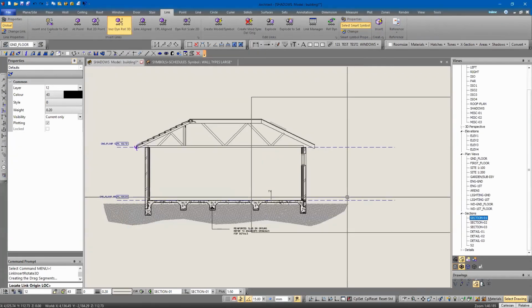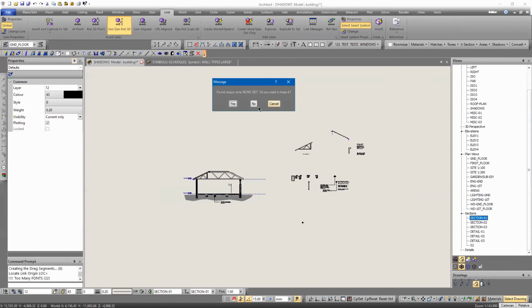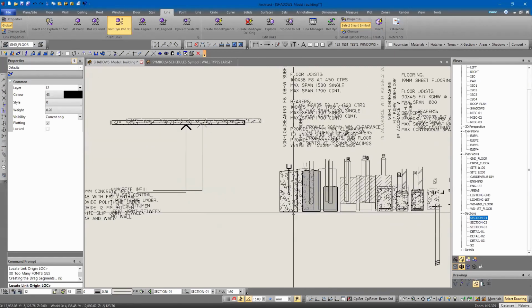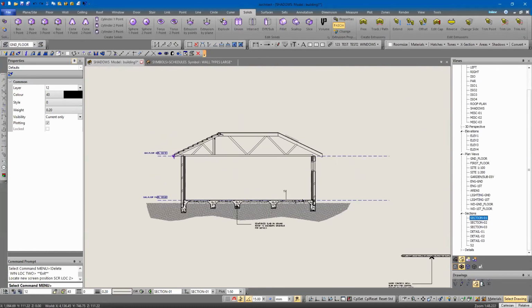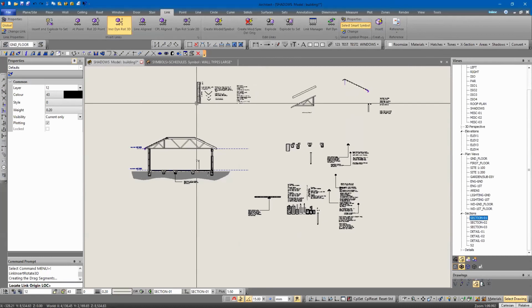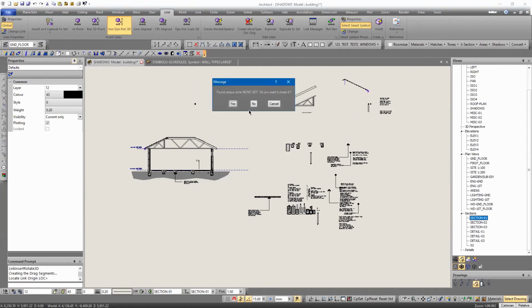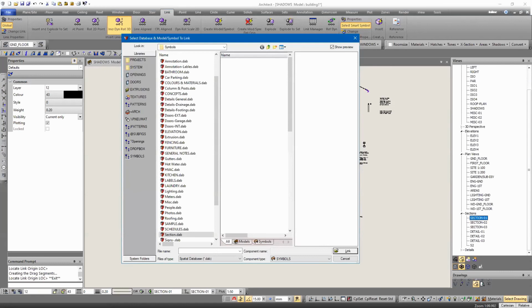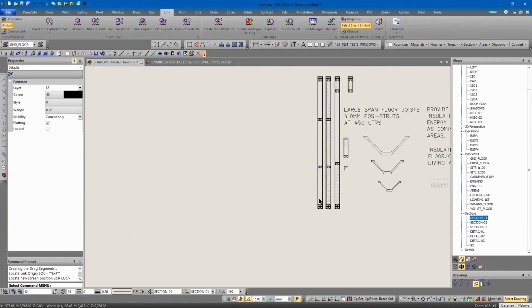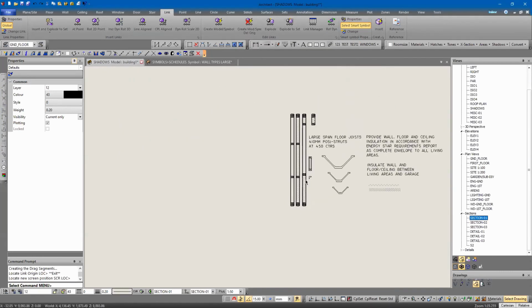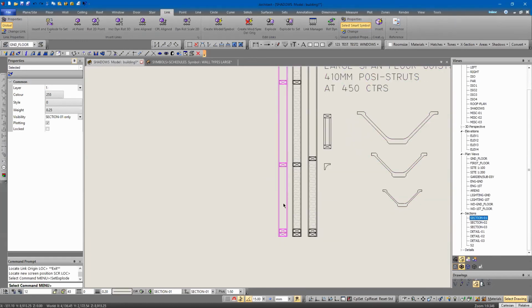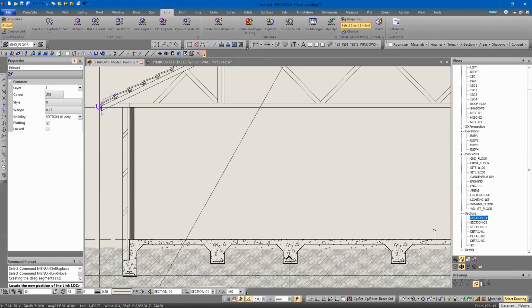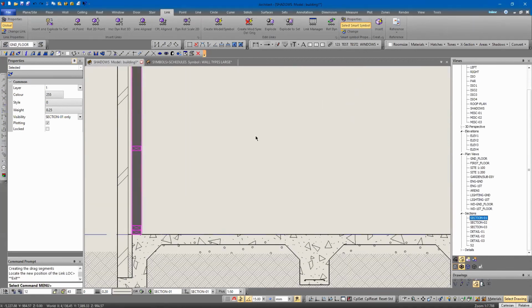We've got a range of things for footings, for stumps. So if we're doing stumps, we just bring those in. So that's sort of the basics of what we do with our section. The main one is using, yeah. So with our walls, we have a predefined section already done with your plates and your plaster and everything. So you can just go move that onto there.